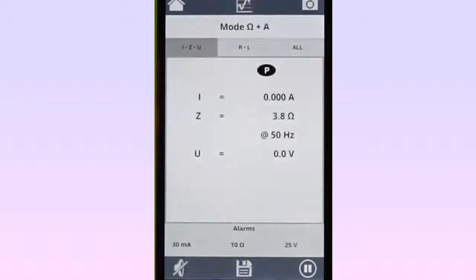When you create a non-graphical text record, you have the option of saving it as a quick data snapshot, or you can include more detail by adding a descriptive comment and a photograph. To do this, display real-time data in text mode. At the bottom of the screen is the Save icon. A short tap of this icon saves the record as a screen capture snapshot. It will now appear in the Display Snapshots list.